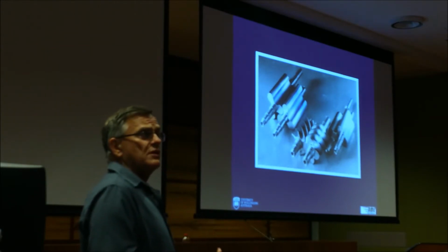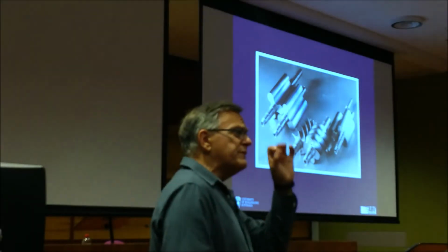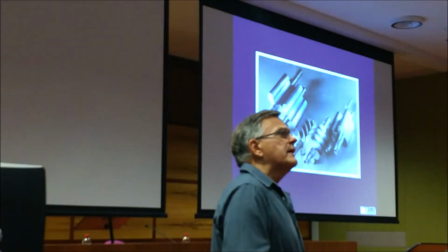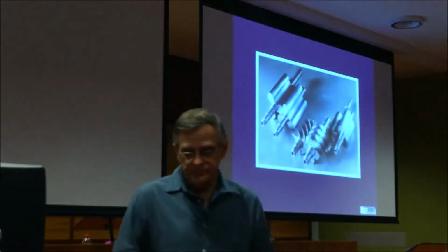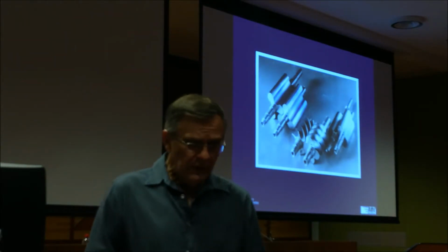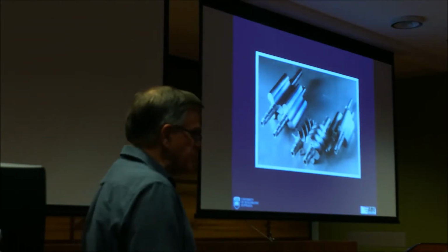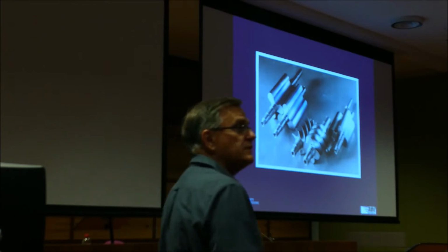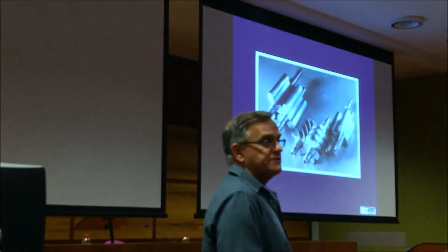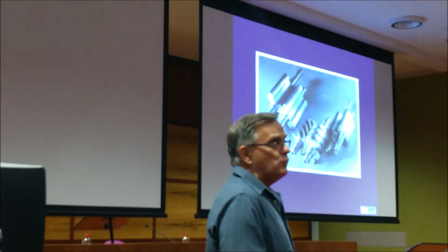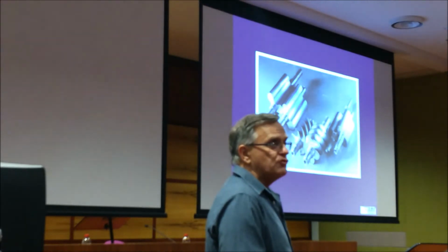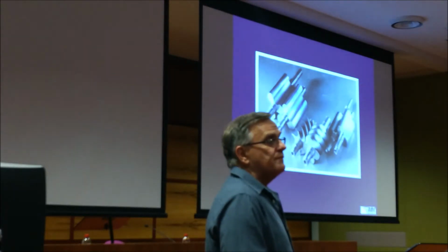Most compressors are also oil lubricated, so you will get a little bit of oil in your air. The air comes in contact with your lubricating fluid. For the food and chemical industries, you can't tolerate any oil, so you have to buy an oil-free compressor. They generally have to be water-cooled, because they run pretty hot. Dry screws are generally used.